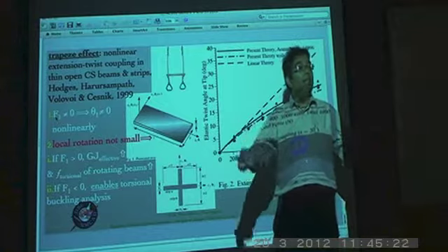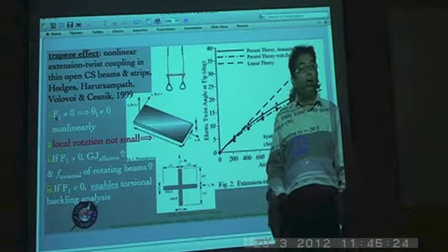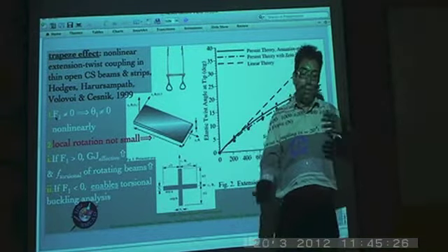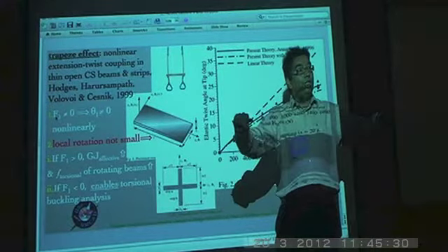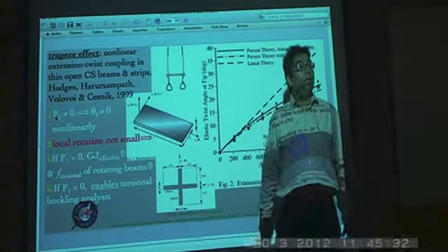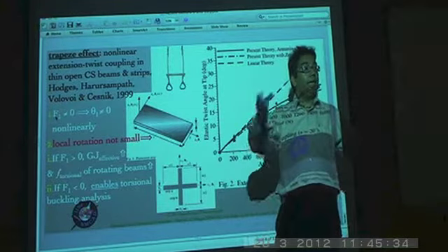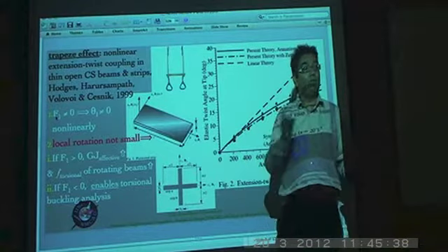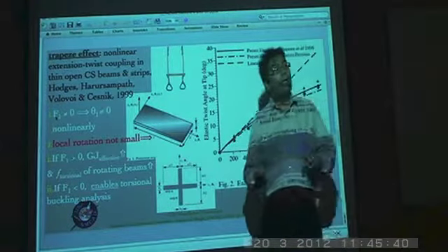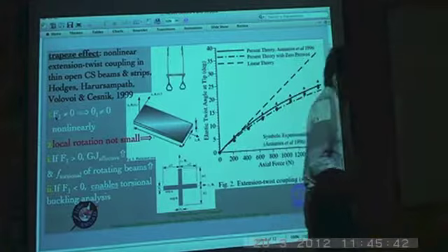So that affects the torsional stiffness, or in other words, it could be the other way around. What we talked about is an extensional load which affects the torsional stiffness, but at the same time it could be a twist which affects the extensional stiffness as well, because S12 is basically coupling in either direction.